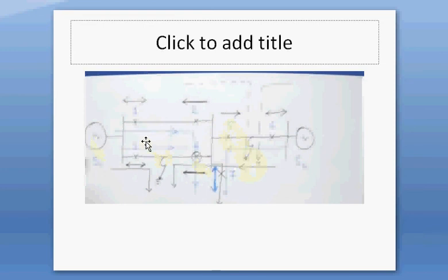Now as the fault occurs in between relay 5 and relay 6, current from generator S1 will follow this path from relay 1, relay 2. Now the current will flow in relay 5, and then it is fed to the fault. Now previously the current in relay 5 is from generator to load, that is from right to left.